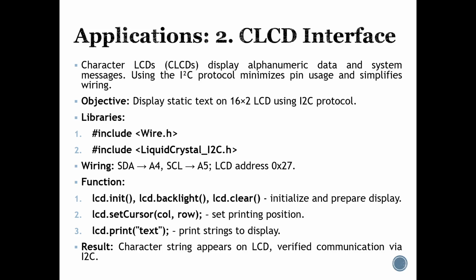Next, I interfaced a character LCD or CLCD using the LiquidCrystal_I2C library. By including LiquidCrystal_I2C.h and Wire.h, I could initialize the LCD with I2C address 0x27 and display text. This interface displayed information like temperature, volume, or device status during the project. It was a key part of user feedback in the system.